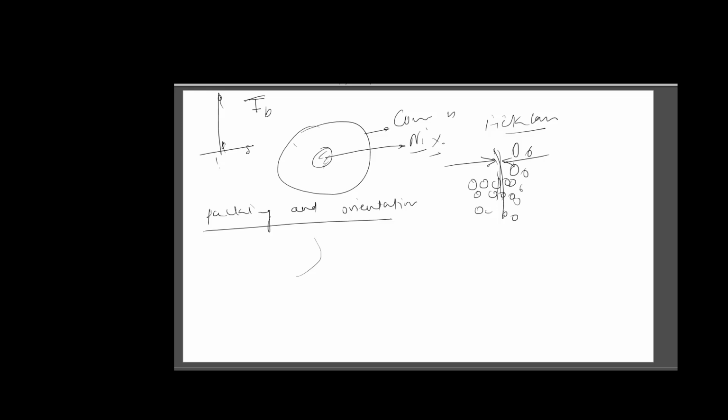This mismatch is the mismatch angle, and this region of orientation mismatch is called a grain boundary. Atoms at grain boundaries are said to be at a high energy level, because every atom wants to decrease its energy and go to the minimum energy. But at these places the bond length is higher, so they have more Gibbs free energy because of the larger bond length.